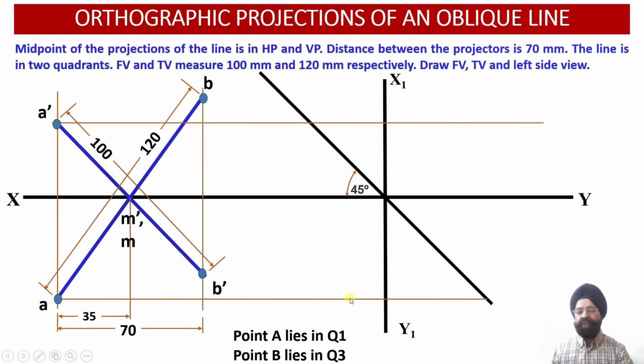And once we extend this horizontal construction line onto this transfer line, we will obtain the corresponding distance in the profile plane over here, because this angle happens to be 45 degree. So this distance corresponding to the top view has been transferred to this distance corresponding to the profile view. So if this distance happens to be x in front of the vertical plane, here we can check the same distance x in front of the vertical plane has been obtained in the corresponding profile view over here.